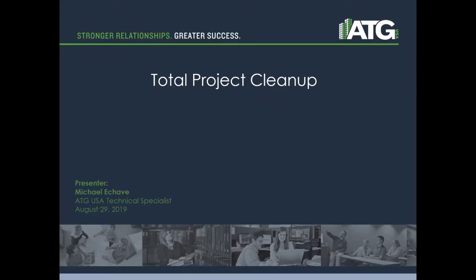We're going to go through two different workflows. We're going to start off doing a total project cleanup in terms of cleaning your project and lowering the full file size. And then we're also going to go into coordination model cleanup as well. In terms of my background, I come from a structural design background, so I'll talk about linking and cleaning up a coordination model from an architect, and then linking that into my model with a lower file size, and then also cleaning up my model to send for coordination in terms of sending it off to subs as well.